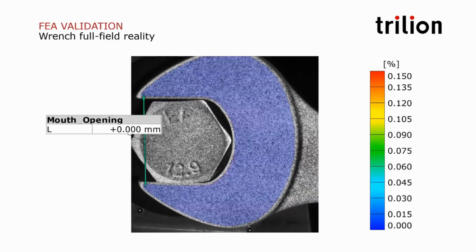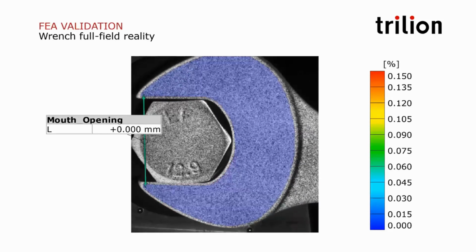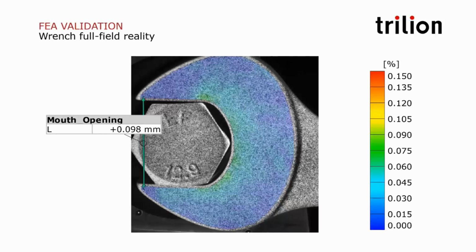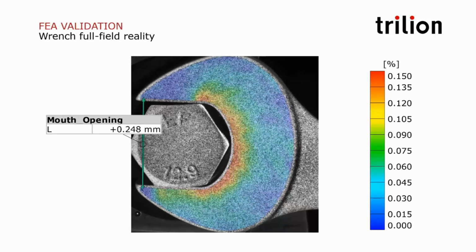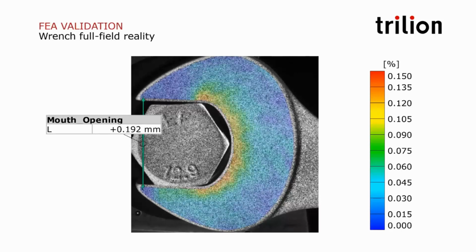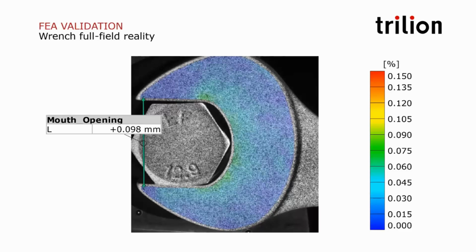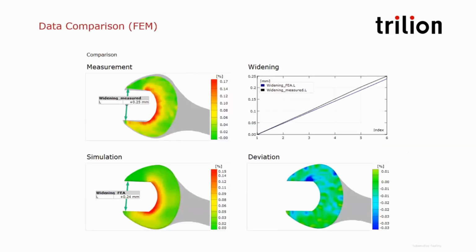But in general, the ARAMIS system results are great to compare to simulation. The data is very, very similar, so we have 3D meshes in both software worlds. And ARAMIS software allows for the export of the mesh to your software. We can export in formats like STL, UFF, IGS, but as you can see on this slide, we can import FEA too. So we work with all the major software, ANSYS, Abaqus, LS-DYNA, and we can build those differences.